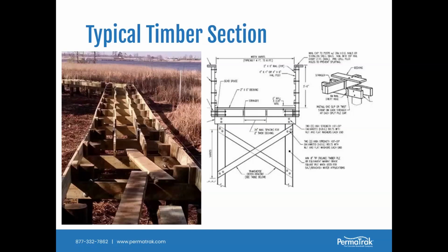Now, the limitation of a timber boardwalk is that typically they're limited to about a 10 or 12-foot span. So think again about your impacts to the wetland. Can you handle those types of impacts? And because timber is not as strong as concrete, you may get more diagonal struts, some blocking, and more members. There are certainly a lot more parts that go together in building a timber boardwalk.